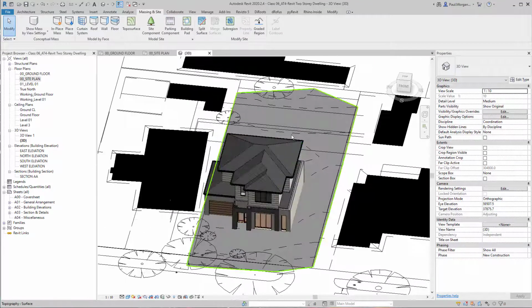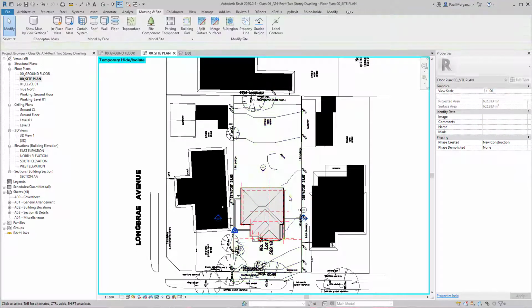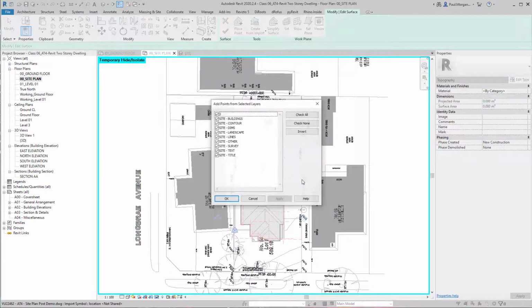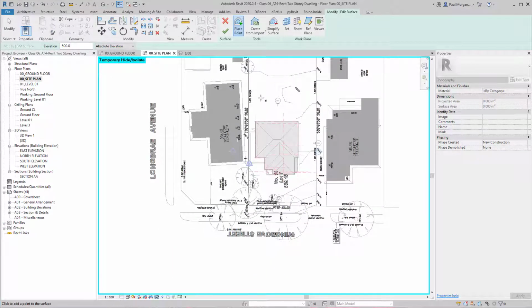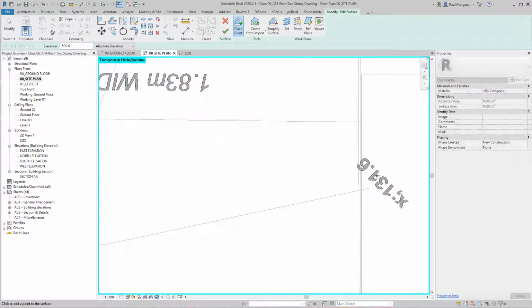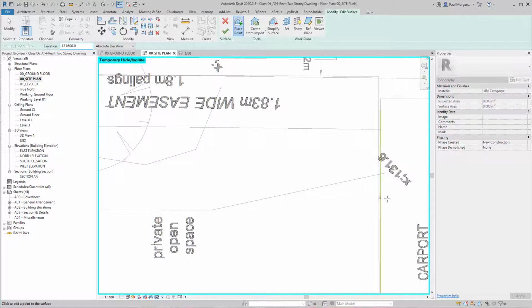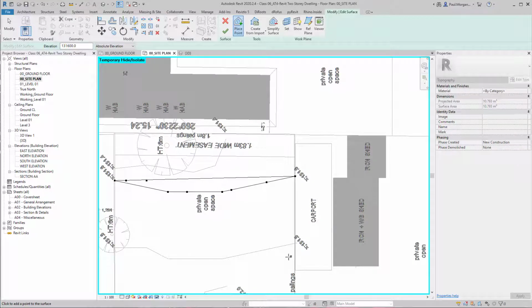So again, if I go back to our site plan, I'm just going to hide this site quickly. The other way that we can create this site is by going Topography, and instead of creating from the instance like we did before, picking the layer, we can still create from points and then manually draw this. So we can say, for instance, what's this number? 131.6. So I can type in 131,600, because that's 131 meters in millimeters. And I can just click at each of these points periodically as I like, follow that contour around, and then type in the next one.